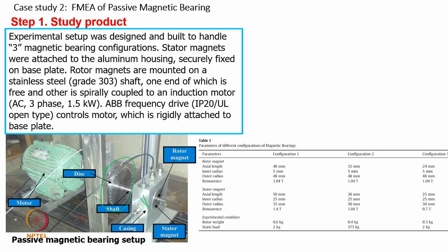Here you can see that an aluminum housing or stainless housing can be utilized, and we have made this on T channels. In a T channel, the housing will be mounted rigidly. If I drill a hole and then mount it, then maybe the rigidity of the housing will be lesser. So, in this case we try to fix the housing rigidly on the base plate, and there is a split housing. You can see the top half of the housing has been connected whenever there is a need.